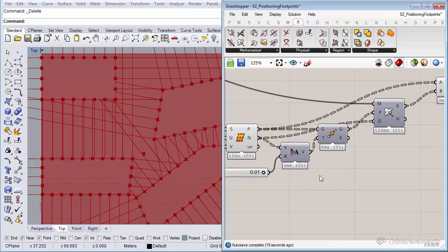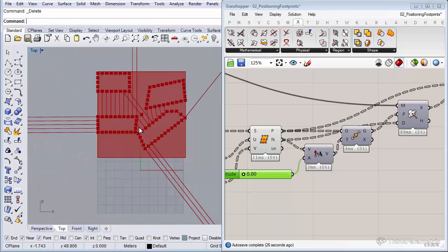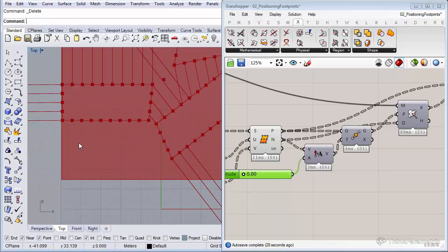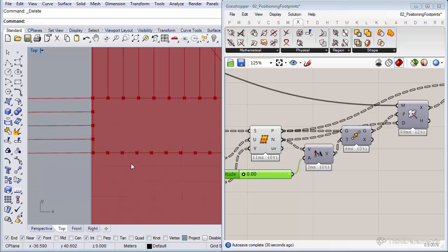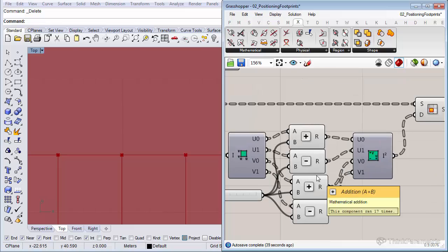And also if I set this number to 0, which means if you wouldn't have offsetted the facade, you see that something goes wrong, because sometimes, I mean, here they got emitted, but here no, they're intersected with themselves. That's why we need to offset them with a very small amount. And the same goes with the shrinking of the surface with a small tolerance.